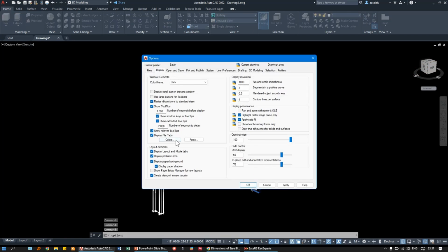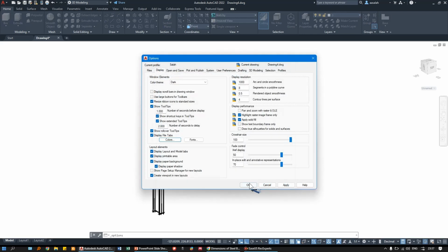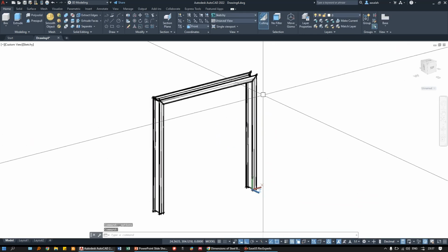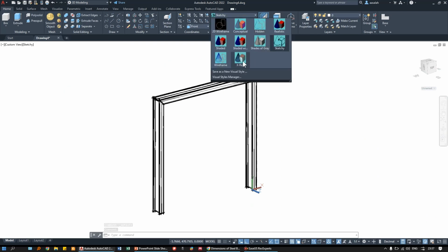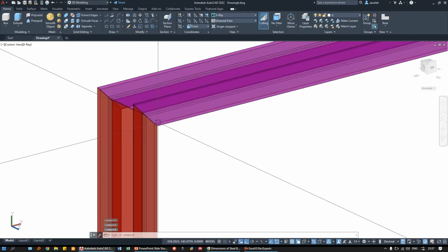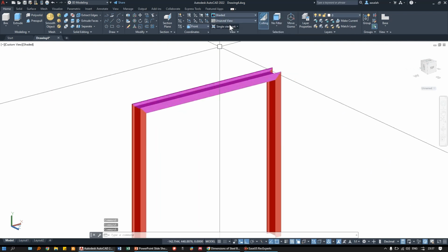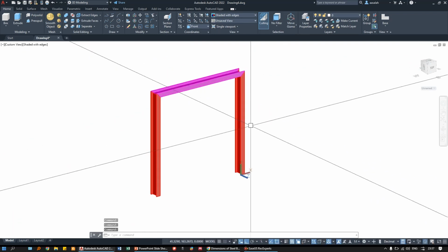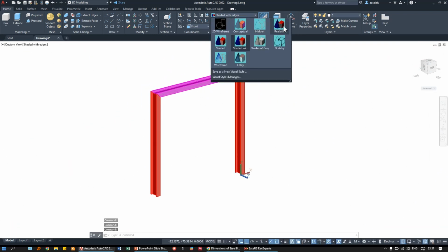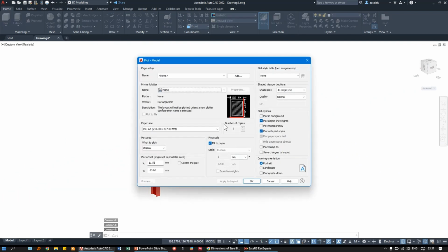As we can see here, we can change the background color to white, so we can see now the sketchy one, how it looks, and this one which shows you what is inside your 3D model. But I'd prefer to use the shaded or shaded with edges because edges are important sometimes to show. The realistic one is the best. I mean, when printing, it's going to be more clear.